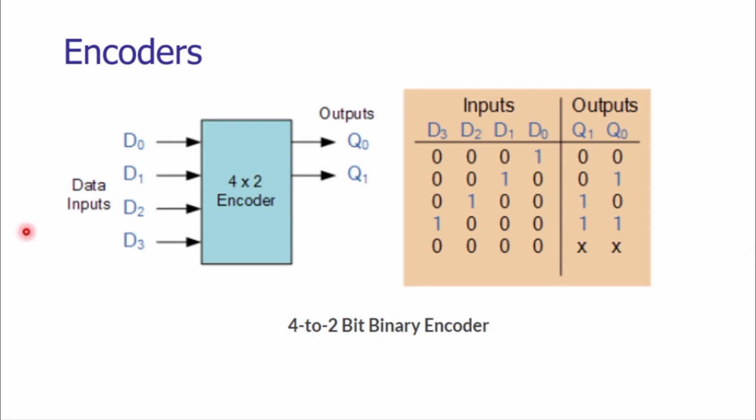These comparators are op-amp based comparators. As we have seen, based upon the input voltage given to the operational amplifiers and the reference values of the operational amplifiers, the operational amplifiers give us a certain output. That output at C0 will be utilized to generate the input data line D0. Similarly for D1, D2 and D3.